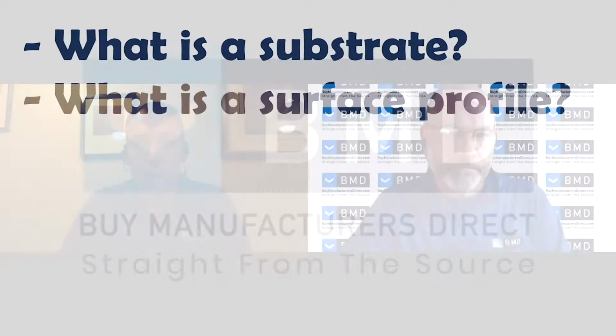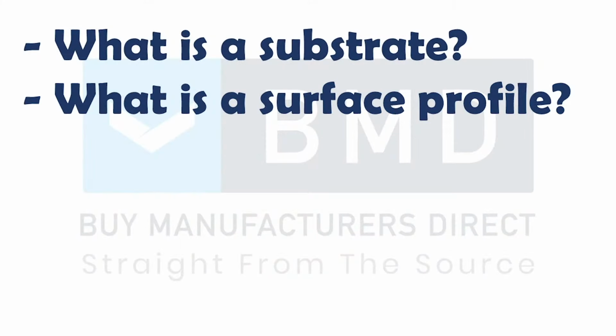Okay. Another term that I've heard very commonly used is surface profile. What exactly is a surface profile referring to? Basically, it's referring to how rough the surface is. The reason that's important is because some coatings, as they cure and cross-link and harden, go from a liquid state to a hardened state, they create tension. And when that tension takes place as the reaction occurs, the profile that's created almost acts like a Velcro. So as that coating starts to pull against itself, we want it to pull against itself as it pulls into the floor or bites into that texture.